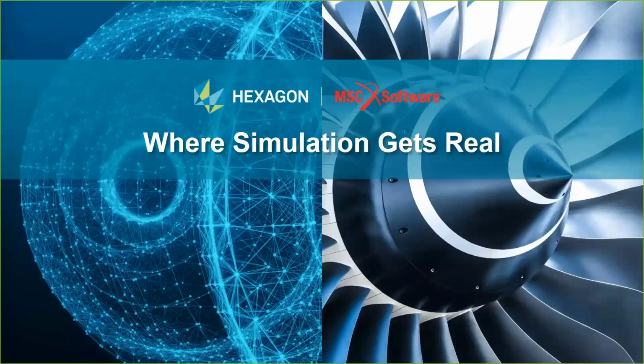Thank you. Another question is, do you have CGAP elements in Apex? I'm sorry, CGAP? Oh, Nastran CGAP elements. The answer is no. Apex does not generate CGAP elements at this time. If you needed CGAP elements, we could create bars, and then those could be converted into CGAPs outside of Apex, but Apex does not support them yet.